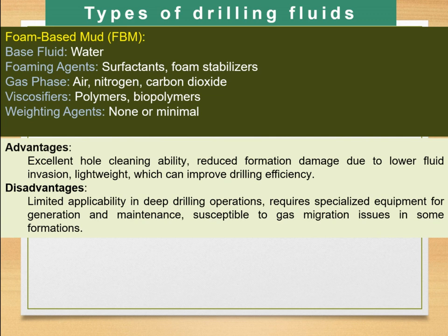Advantages: excellent hole cleaning ability, reduced formation damage due to lower fluid invasion, and lightweight which can improve drilling efficiency. Disadvantages: limited applicability in deep drilling operation, because in deep drilling formational pressure will be high, so this cannot be used.